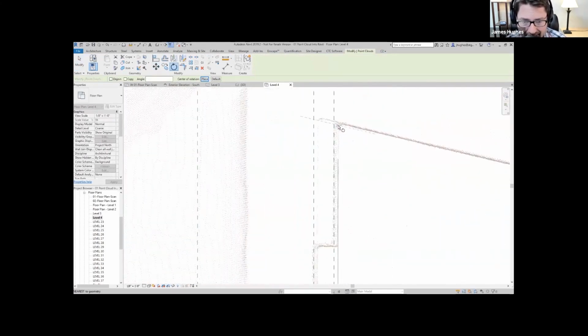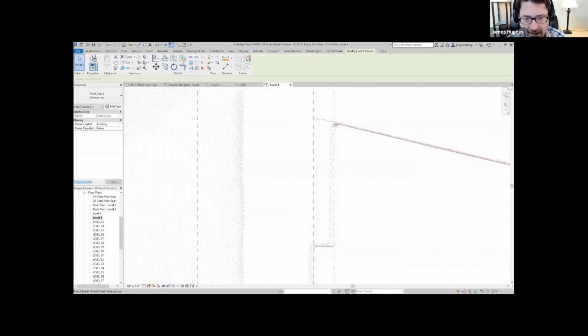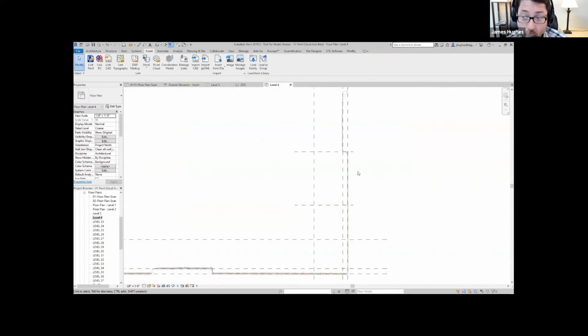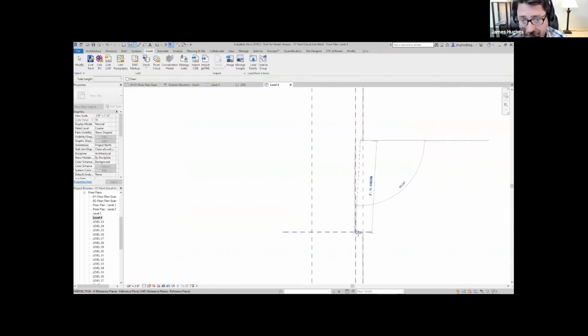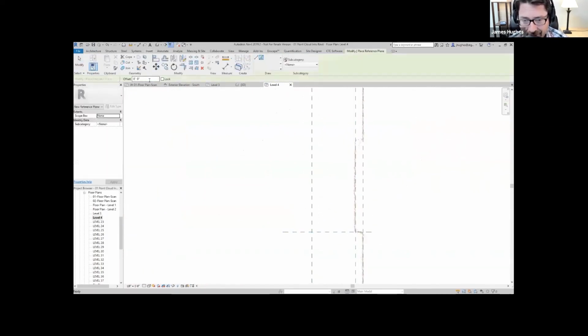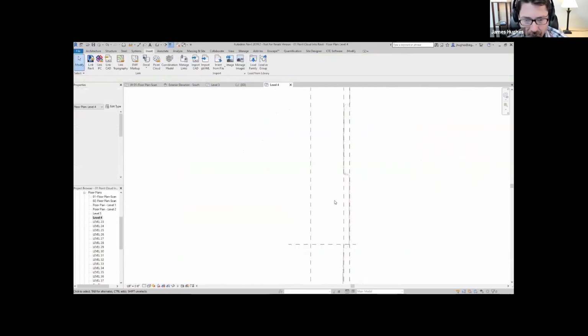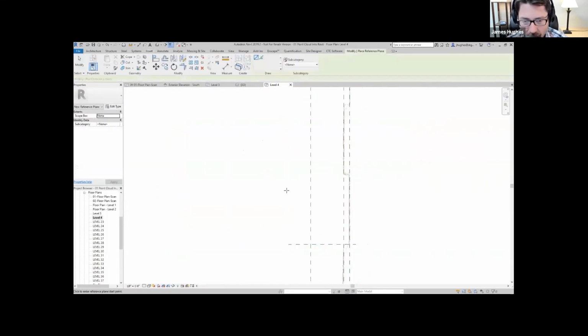And now you can see that in and out undulation that the limestone has at each window piece. And that rotation is only about 1 inch over about 400 feet. So it's a very precise check there to make sure that we get this thing where we want it before we start modeling elements.